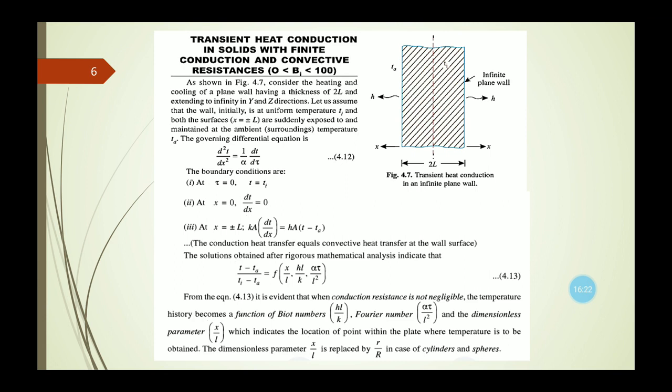Now as this plane wall extends to infinity in the y and z directions, the governing differential equation will be only in the x direction. It is a one dimensional heat conduction equation, that means del 2T by del x2 equals 1 by alpha del T by del tau.